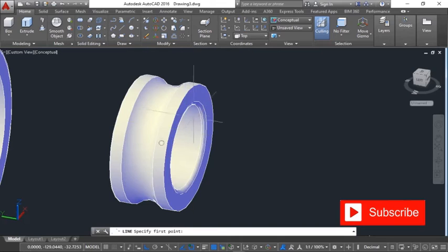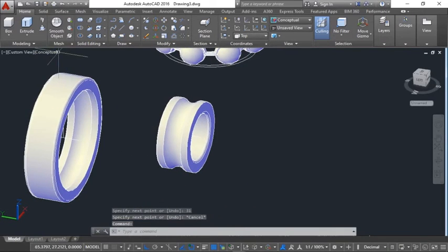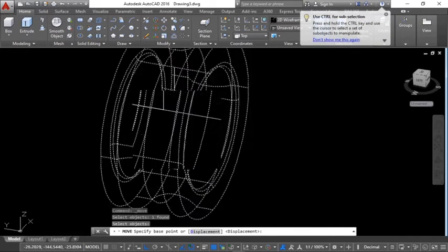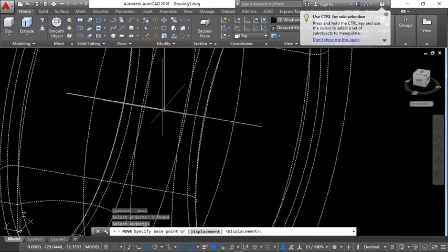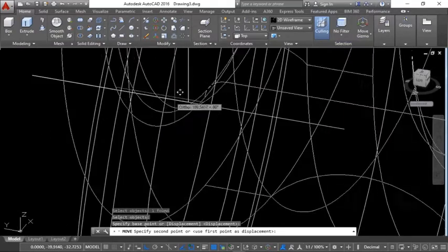We're gonna do same here. We're gonna have a reference here. You see there are three multiple centers there, but I want to choose the first one here. All right, so distance of 31. Okay, then escape. So change this to wireframe, select this, move this. So you're going to know the reason why I drew that line. I'm gonna pick the center of the line that we drew and fix it at the center of the other line here. You have to snap.